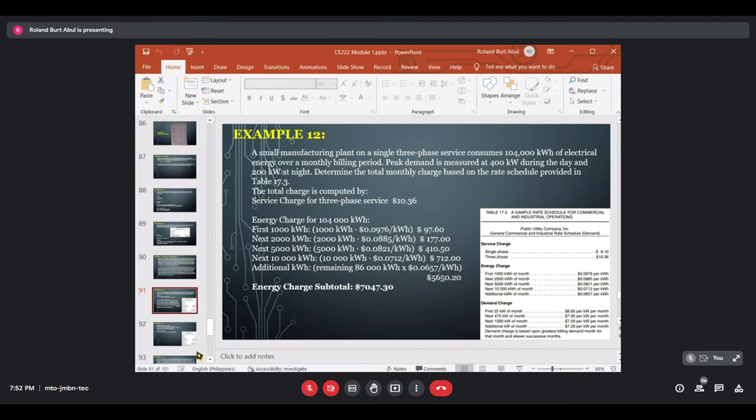The demand charge would now be based on 1,200 kilowatts. On some billing rate schedules, the demand charge will remain at that rate for 12 months, even though this increase in demand occurred only once for a 15-minute period.